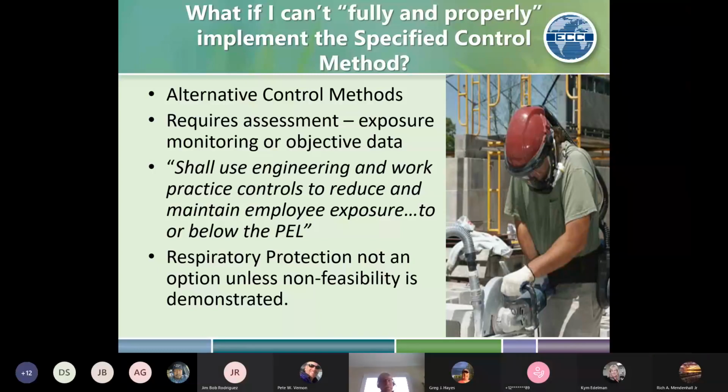The way the cyclone works is the air enters the cyclone first. It gets spun around, and the action of the air flowing around and coiling through the cyclone causes those larger particles to impinge on the walls. They don't stay in the airstream. They bounce along the walls until they finally lose all that inertia, and their mass causes them to drop out by gravity.